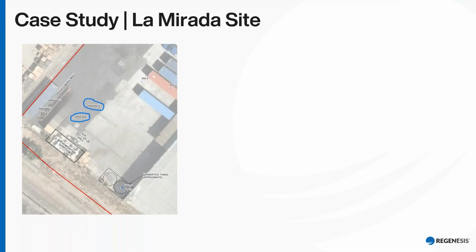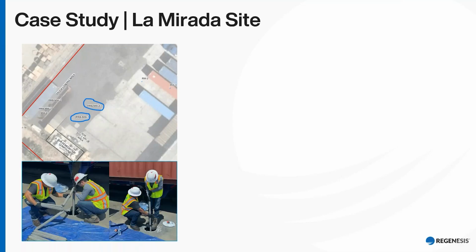In one of those wells, flux tracers were deployed, and this is the deployment. Of course, flux tracers, which is the flux meter that we offer at Regenesis, are sent ready to be deployed. It's an easy deployment. They are canisters that are 2 foot long. They are deployed. Then after 2 weeks, they were retrieved and sent back to the lab, which allows for an easy installment, retrieval, and short processing. Then once they are in the lab, we are in charge of the breakdown of the devices, as well as the sampling, analysis, and reporting.